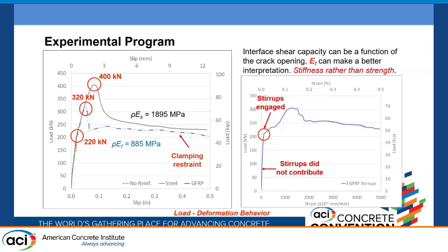Okay. Yes, indeed, the results that I am presenting today are just the first phase of the project. In the second phase, we performed additional tests using cold joint conditions in order to study the performance of the GFRP, mainly post-cracking behavior. In those results, we have seen that the contribution of GFRP is affected by the cold joint, so it is reduced a little bit.